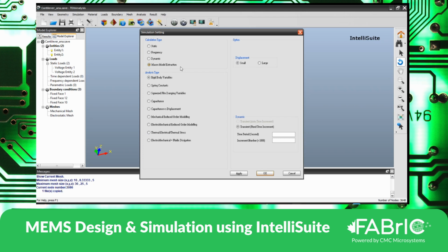Okay, so here, just to give a glimpse, macromodel extraction is a simulation where we can extract many parameters like spring constant, squeezed film damping variables, capacitance versus displacement, and rigid body variables.